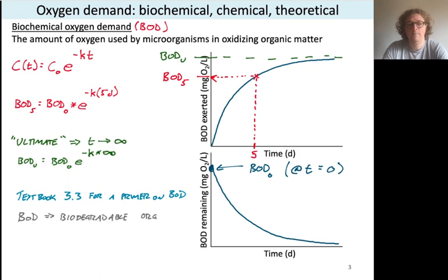Finally, just a note that organic matter being degraded by microbes is perhaps the largest source of oxygen demand that we'll deal with, but it's not necessarily the only one. So in addition, we often describe chemical oxygen demand, or COD, and you could think of this as a totally inorganic process. So if there aren't microbes involved, it's simply a chemical reaction that consumes oxygen. You'd put that in your COD category.